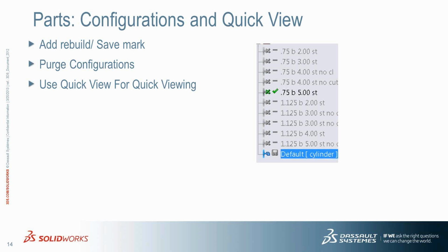Now when it comes to configurations, when you load a file, if you're on a version previous to 2013, as soon as you activate a configuration, it loads all the data for that configuration. So let's say you've been sitting with a file most of the day and you've loaded half the configurations, 6 or 7. Well, now you have what's equivalent to that part open 6 or 7 times because all the configuration data is currently loaded. Well, they've added some tools to actually purge the configuration data to get it out of memory.